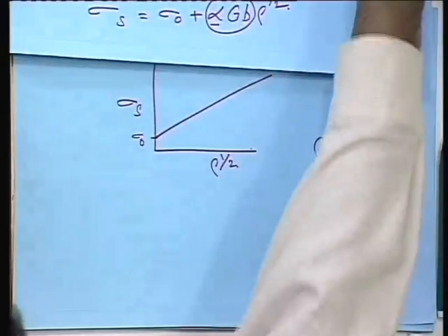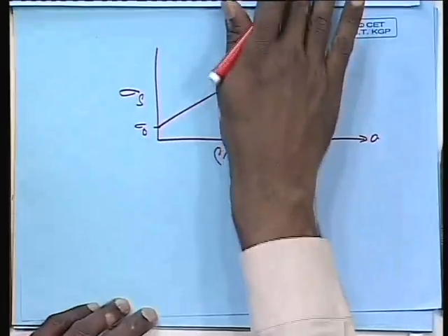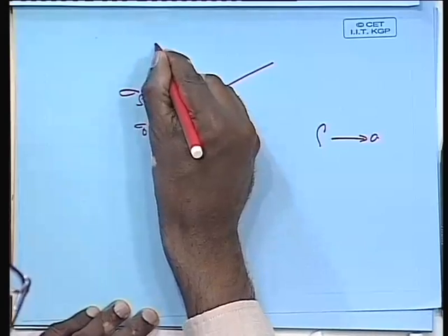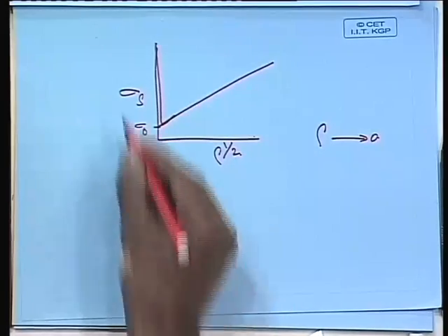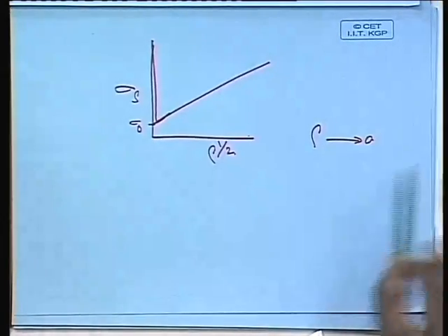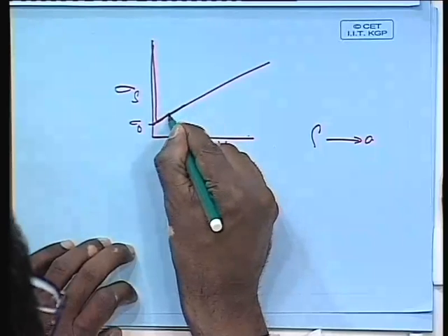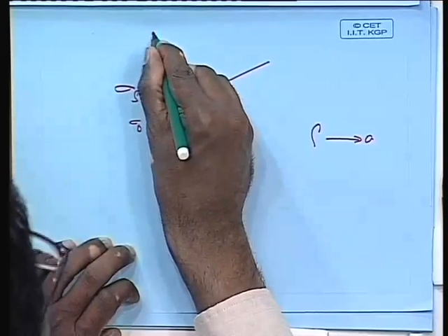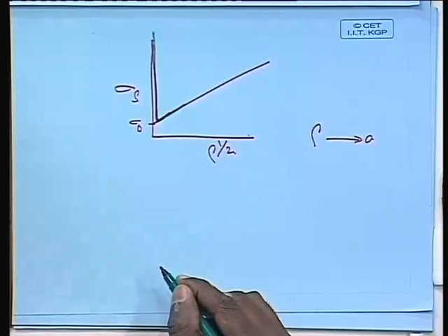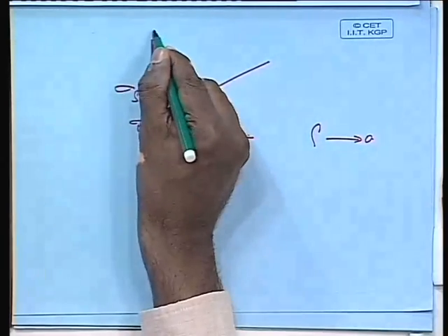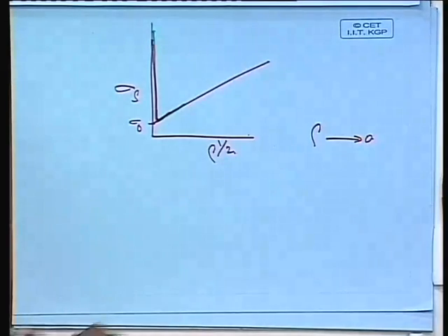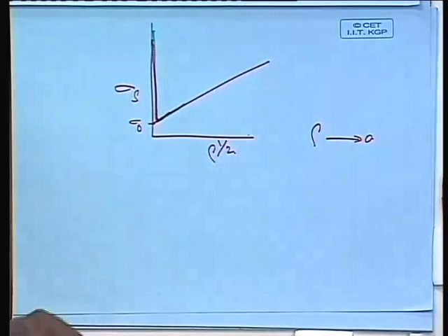And so in principle, the curve should go more or less exponentially up in the zone very close to 0 dislocation density. It goes very steeply up and reaches the value of theoretical cohesive strength when the dislocation density goes to 0.